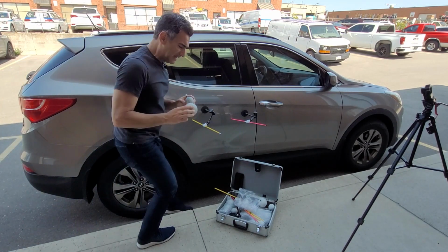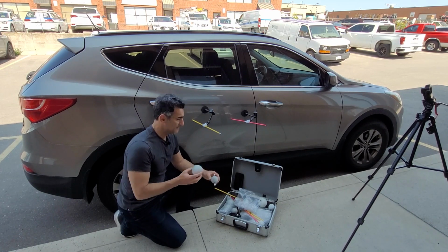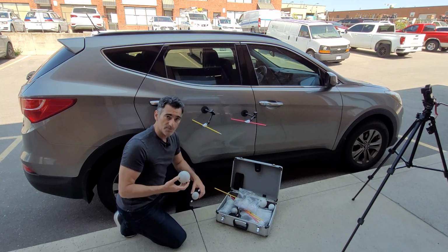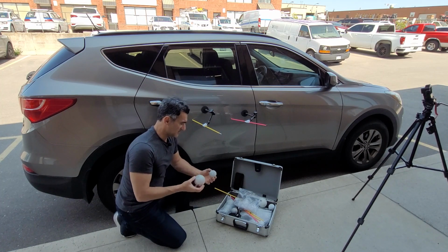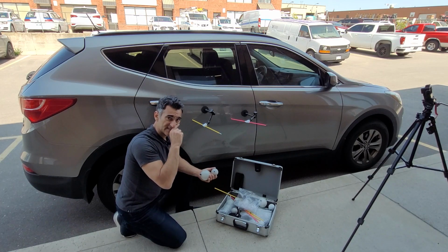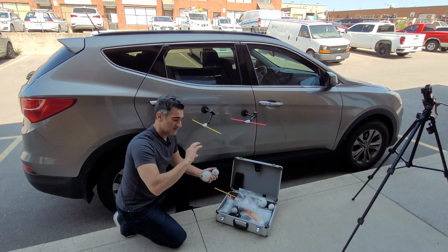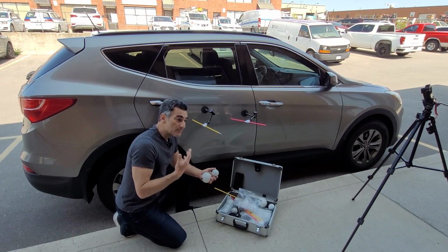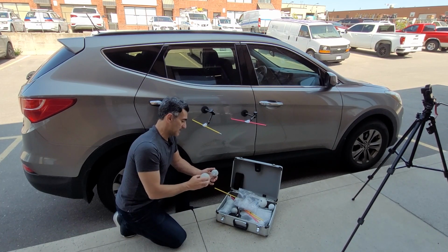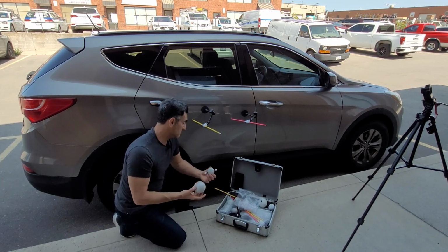So these spheres are very useful, especially if you were going to be doing just photogrammetry. Being able to see all this random texture on the sphere helps significantly to resolve the surface. If this was just a plain white sphere and you're photographing it from a number of different sides, it's very difficult to determine where the surface is because it's just white. There's not a lot of neighboring pixels or texture or random contrast that will help to determine where a point exists in 3D space. So having this random texture tends to help.